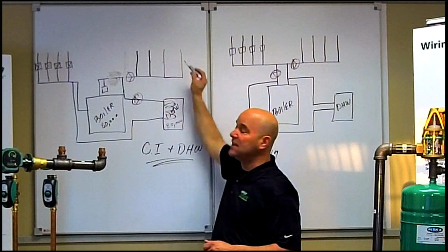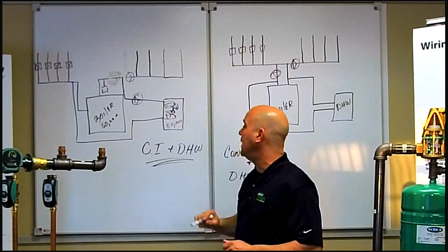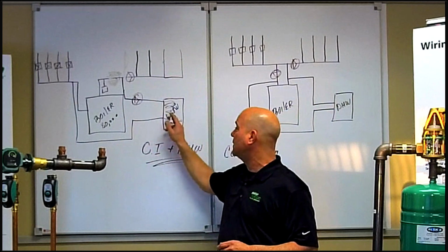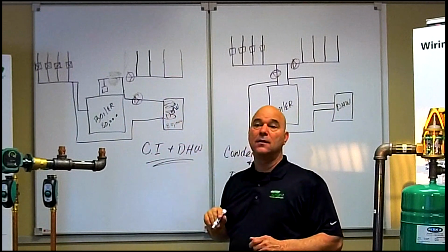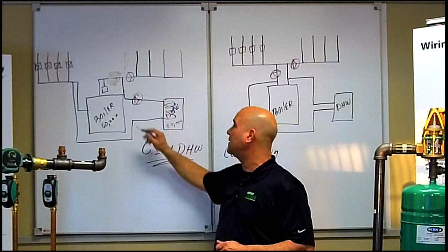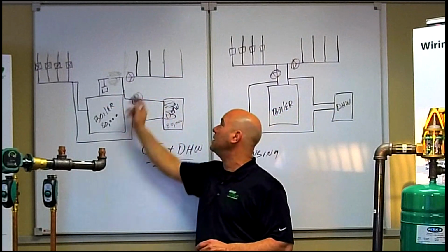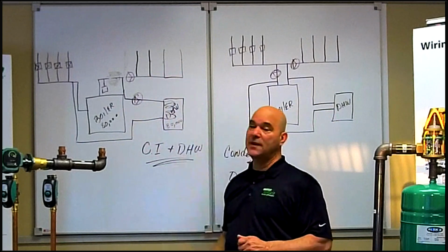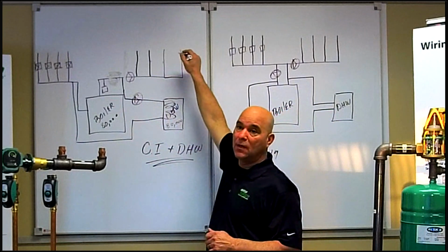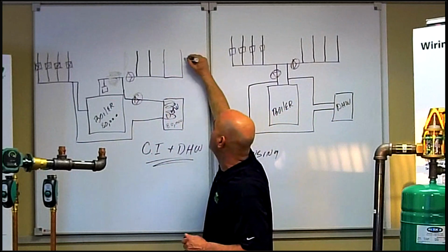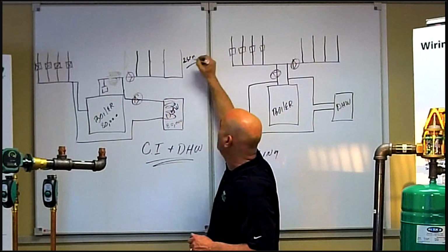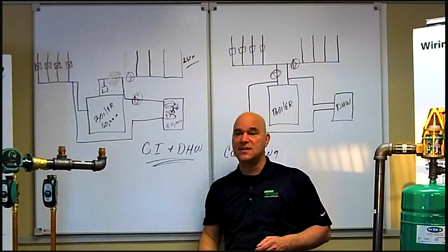Each heat circuit, what size would that have to be? And you can fire it off to Jim what size our piping to our domestic hot water, the indirect, would have to be. So pipe diameter for the indirect, pipe diameter for the header and return, and pipe diameter for my 4 heat circuits. So the heat circuits up here, we know they're 2 GPM, so this is 2 gallons per minute. There's 2 different answers we'll accept there.